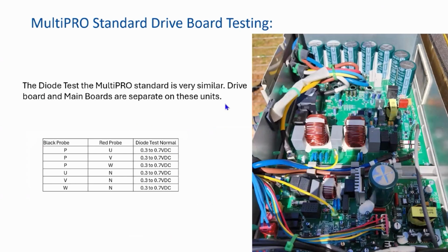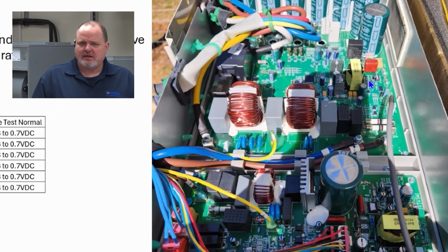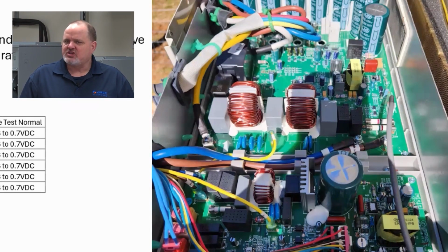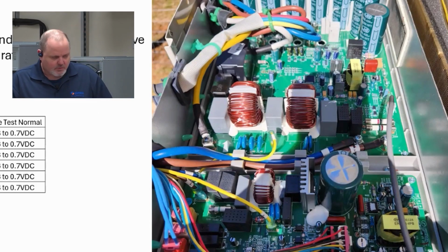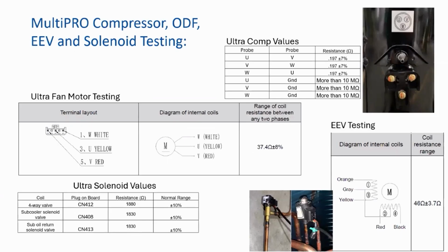If you look at this board closely, you come over to the discharge points. It's right up in here is where you measure the DC bus. The DC bus is P and N, or discharge points. Sometimes those are what they're called. So it's a pretty simple test to do. I'm going to demonstrate it to you on another board here.